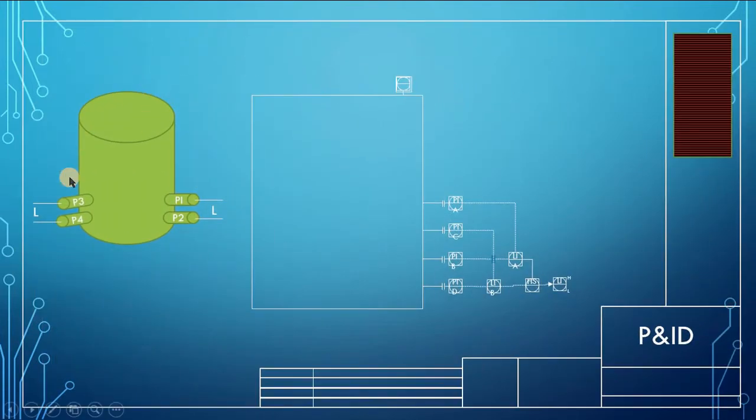Another example: if you have a tank and this tank has a variable density fluid in it and you want to measure the level, you can measure by different methods. One of them is the pressure. Now assume you have a foam or something on top of the fluid. You may say a measurement from the top would not be very reliable. I need to measure, let's say, the pressure from the side.